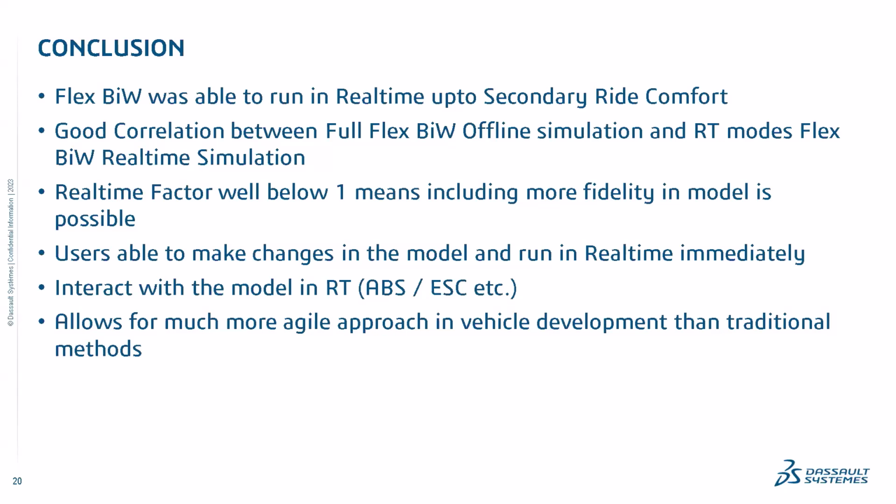Of course, users in this case were able to make changes in the model and run in real time immediately. If you remember, in terms of the requirements, the main requirement was that we should not be simplifying the model in any way. So we had the same component-based model running in real time, which means that you could change any hard point or any bushing property file or spring and dampers. You could even swap components as well. So this was quite a strong advantage that one could get out of these component-based real-time simulations, basically interacting with the model in real time.